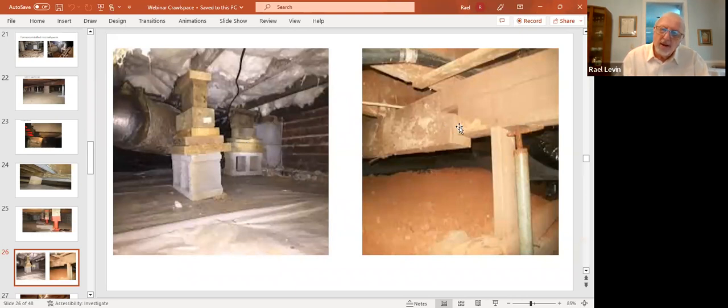This is an old carpentry method that was used to join joists in order to get a longer span, where they'd have actually mortise and tenon, they're notched out and nailed to each other. Don't see that around anymore. Most of our floor joists now are engineered wood and I-joists and trusses, but this would have needed a support on this side as well. And this one's actually being held up by a 2x4 temporarily. And as you can see, even the metal one, there's still moisture there, so it's rusting.